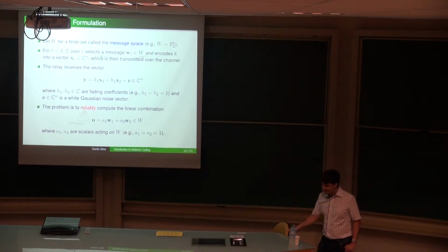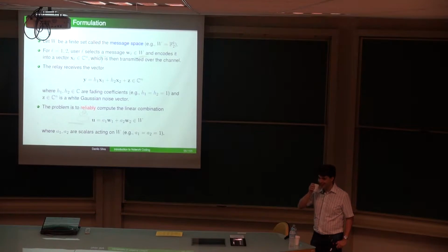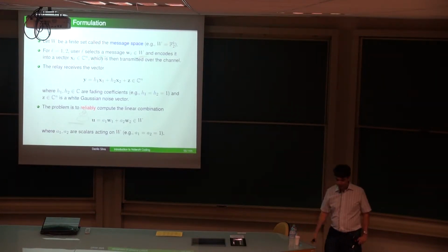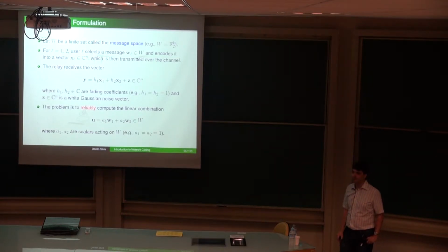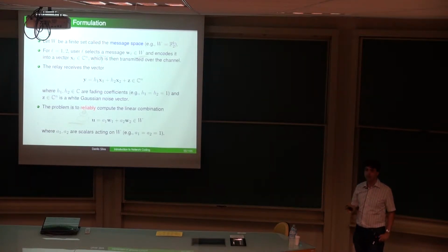Yeah, it's easier, right, to work over the reals. So that's a starting point. But probably another important reason is that for a point-to-point channel, so you have just a single transmitter, if you know the fading coefficient here, it may be complex, right? But you can just compensate the phase, right? So just compensate and make this coefficient real.